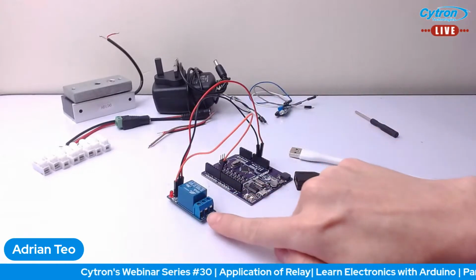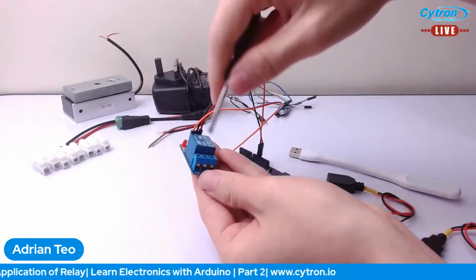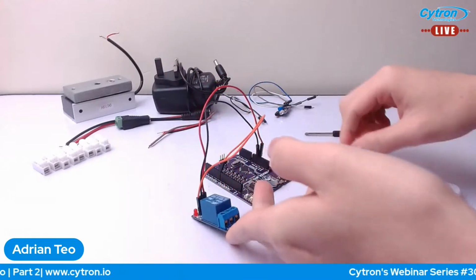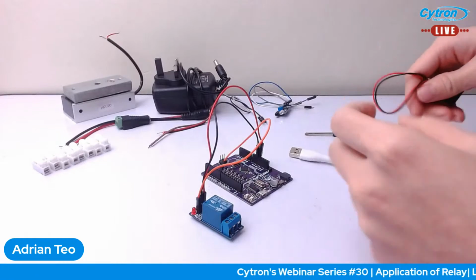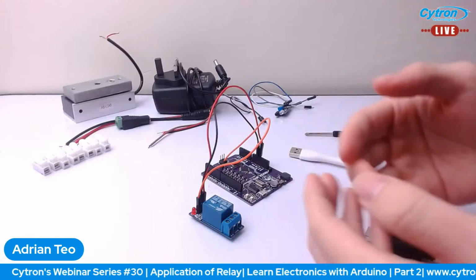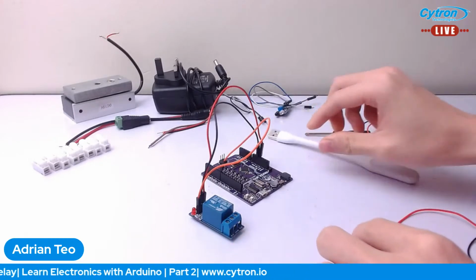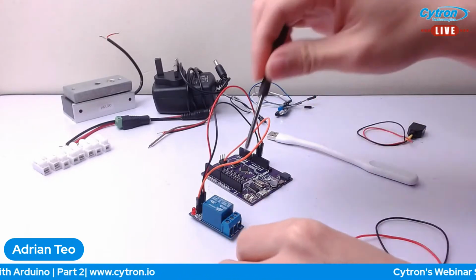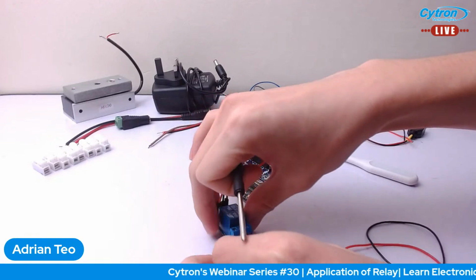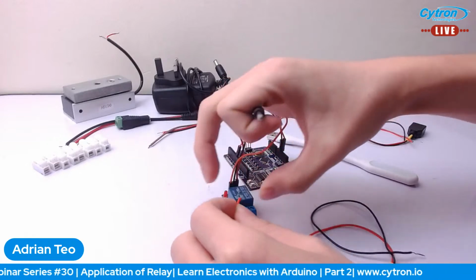So next, I have to connect my relay on this side. So what do I need to do? First, I will release the terminal. And then next, I will pass the voltage. Let me just uncoil the wire. So I'll be bringing 5 volt to this guy. Okay, I will pump 5 volt here. But first, I have to connect it here, this way. So this is the positive voltage.